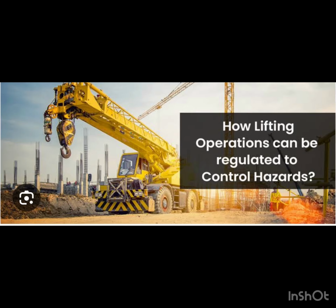Do not stand under the suspended load. Outriggers shall be completely extended. Safety devices should be used. Check ground level and outrigger pads.